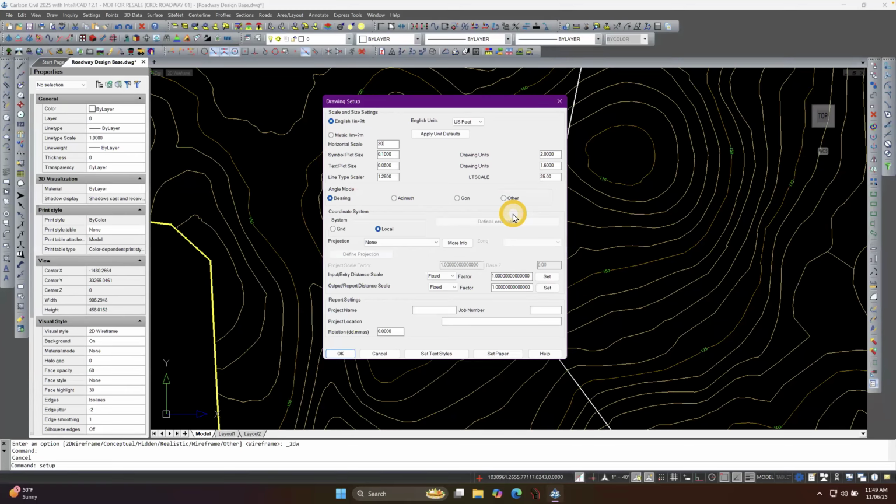However, if you do something like this, I'm going to change this to be, instead of 25, I'm going to go into this field and directly set that to 1. I'm just going to make it a unit size. Now that says my line type scalar is 0.05, but that's not really what's going to go on, because when I finish this, I'm going to do another setting. So I've got this LT scale of 1. Say okay.